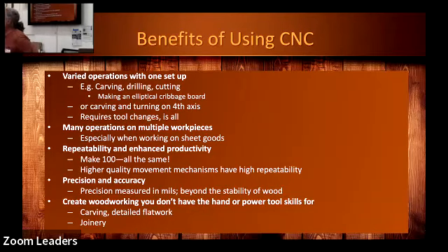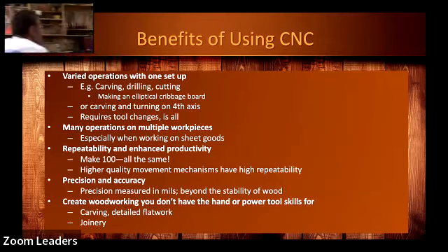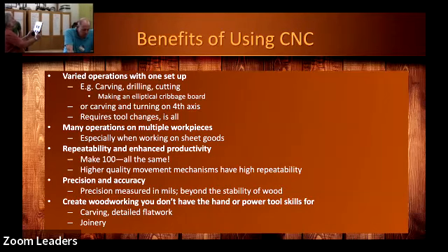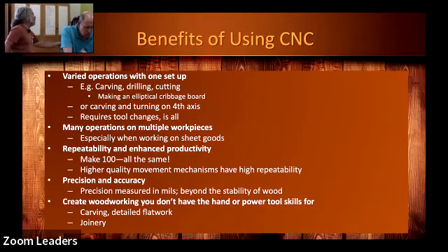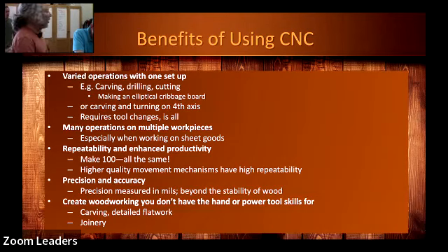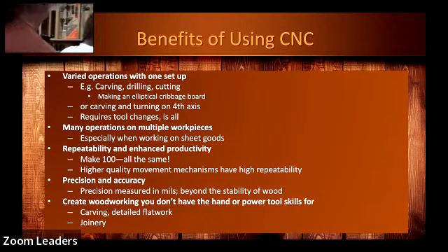If you want it to be perfect, well, I don't know, is this corner square, or does it have a little radius in it? It's from the slab table class. Zoom guys, we've got a piece of material here we're going to take a look at. That's the pattern. And that's the pattern. We could do that. So you've got radius in the corners, even the tight radius in the corners. That looks like, I don't know, 1/8 of an inch or 1/16 of an inch radius. We've got bits that we use typically that can go down to 1/32 of an inch. So we'd be able to cut that on a CNC machine, I think, without much difficulty.